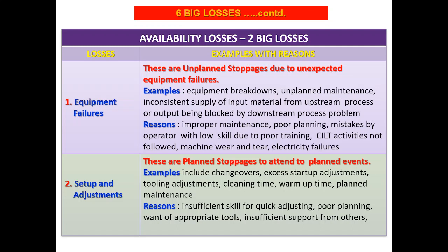Reasons are improper maintenance, poor planning, mistakes by operators with low skill due to poor training, CILT activities, that is cleaning, inspection, lubrication and tightening, not followed strictly, sometimes machine wear and tear, and electricity failures.